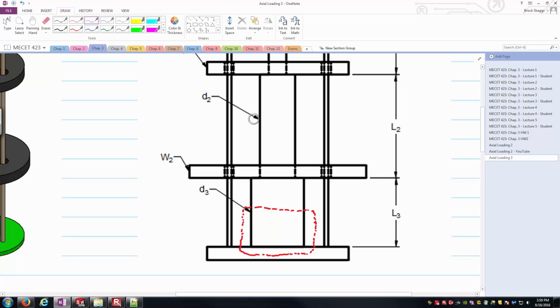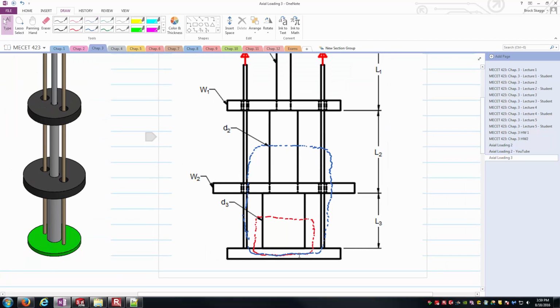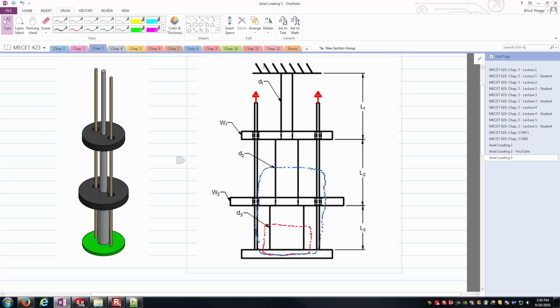And so I'm going to expose the cross section right in the middle of section 2, just like so. And here, where are my other boundaries of the free body diagram? Well, I'm going to take this all the way down to the exact same boundary that I had for my first free body diagram of section 3 down there. So it's looking just like that. And one of the reasons I keep going all the way down to the very bottom of the shaft is because I don't want to find the reaction force where this thing's attached to the ceiling.